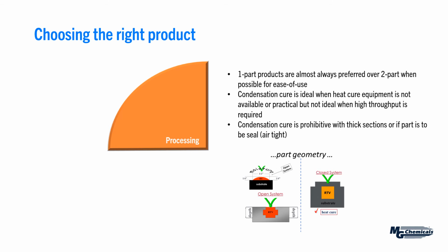Now condensation versus heat cure, well, we went over that as well. Condensation cure is passive cure. Provided the environment is not too dry, you simply apply it and let nature take its course. So of course, it does take quite a long time, and there's very little you can really do to influence and speed up cure. So that has to be something to consider versus an addition cure where you can have more of an impact. If high throughput is more desirable, you might want to look at an addition cure, where you can in fact speed up the cure.